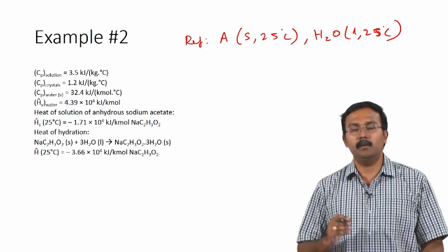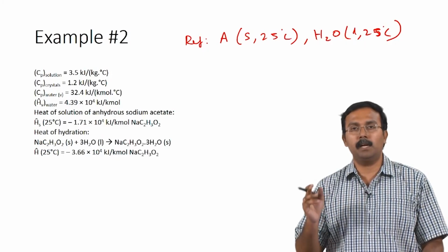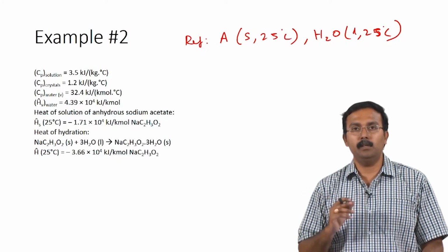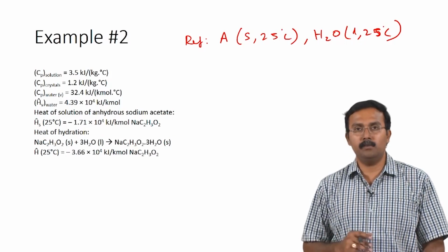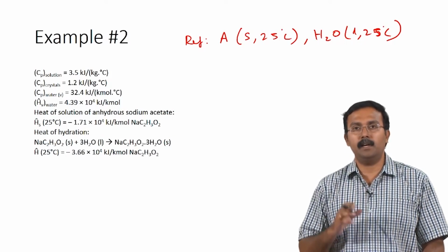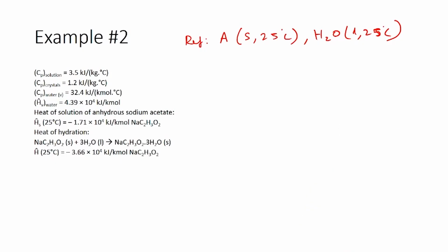However, here we have different solutions and we cannot use one term that can be multiplied with the specific enthalpy. So, we need to look at the process in a more comprehensive fashion. Let us look at the individual components and try to identify the change in enthalpy for the individual components. The first component we have in the system is the feed solution. So, let us start with identifying the change in enthalpy for the feed solution.